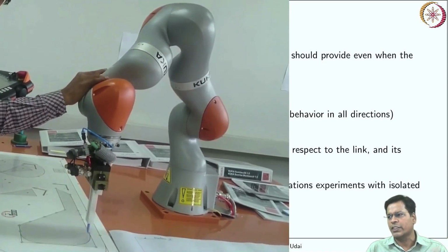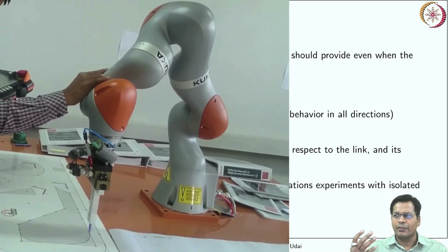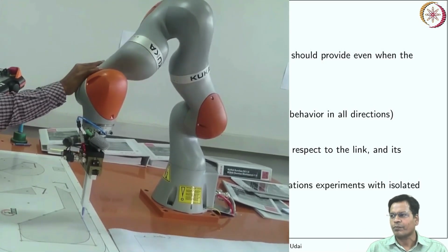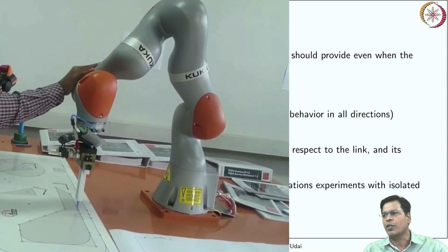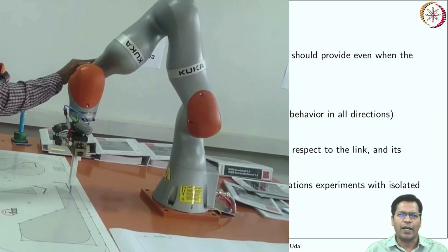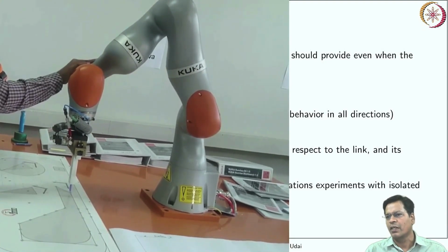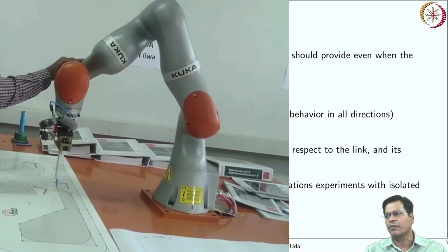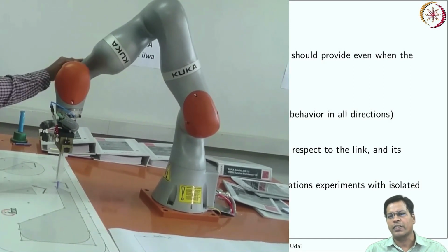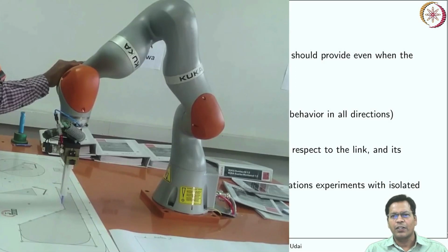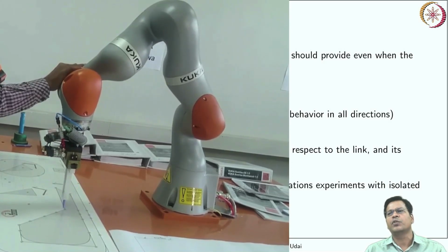The robot controller doesn't feel as if there is any mass of the links. It is as if it is in space. If you take this robot to space where there is no gravity, there is no influence of gravity on the links, and finally it sees no torque at all. If you move the robot, it only requires the torque needed to dynamically move it.